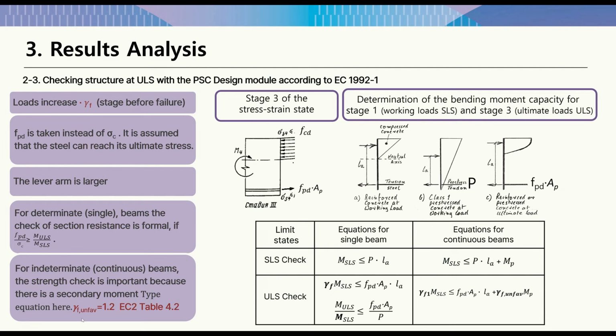And secondly, it can be present in this section without tension reinforcement. I repeat that the secondary moment can be in the section in the absence of reinforcement in it. And thus, the restraining moment does not fully depend on the presence of reinforcement in the section. And we can't conclude that it will increase as much as the force in the cable. This is when we place the force in the cable by the design resistance of steel.